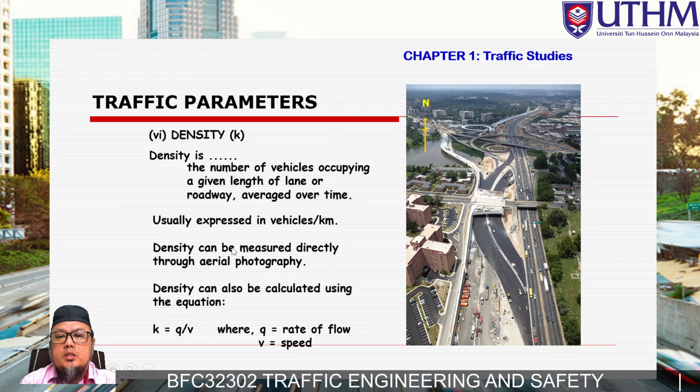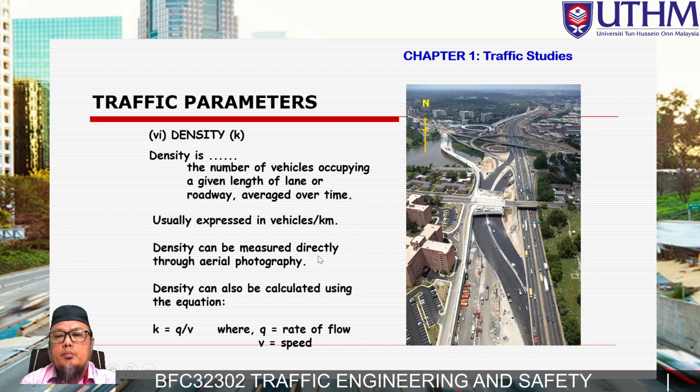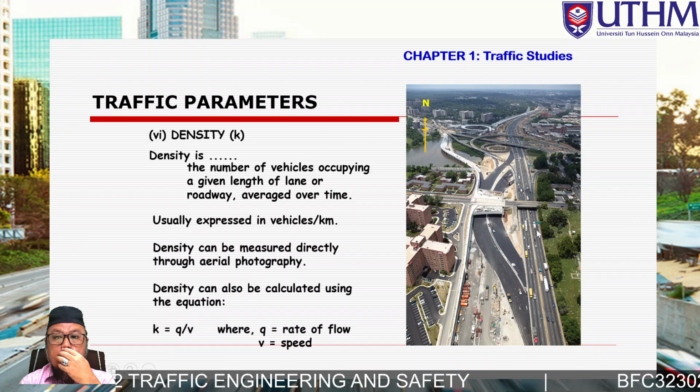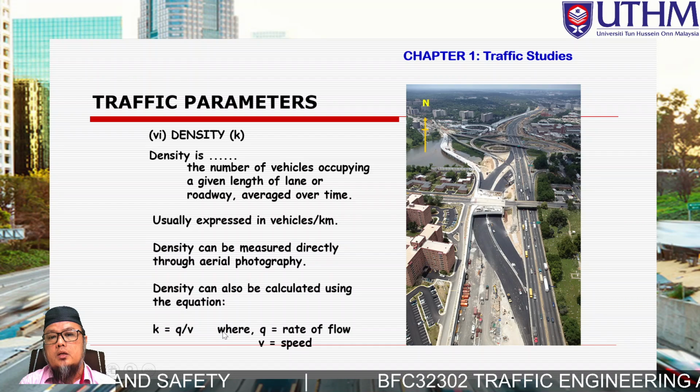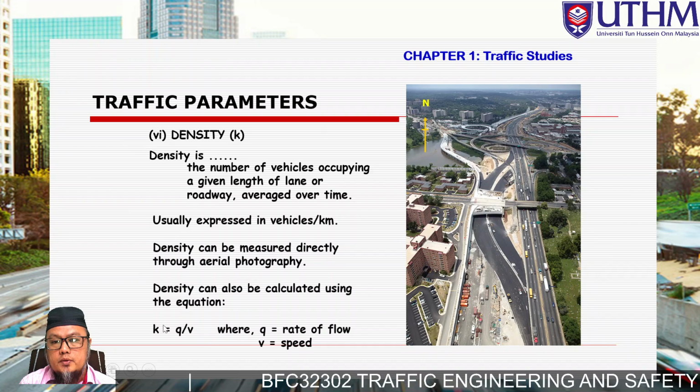Okay, density can be measured directly from an aerial photo. This one, they give an example from an aerial photo. You can use a drone now, simple to operate, and capture the scene of the traffic at any location. From there, you can calculate manually to determine the density of vehicles. Or we can manipulate from the basic formula, which is from K, here we have K, but the basic formula for